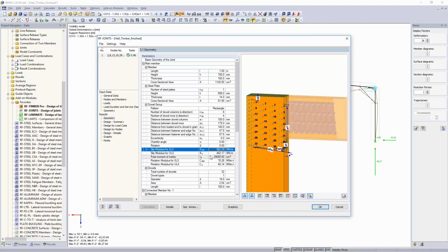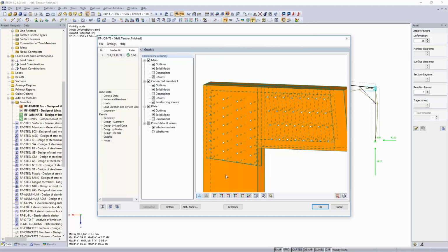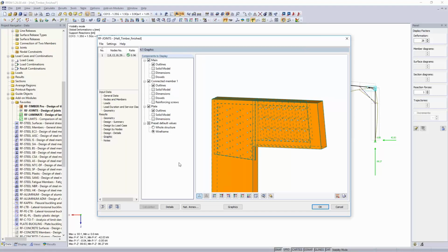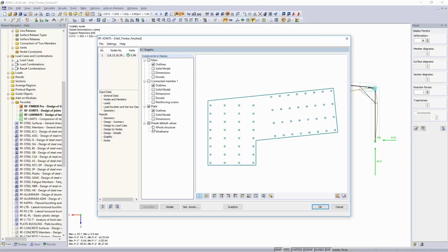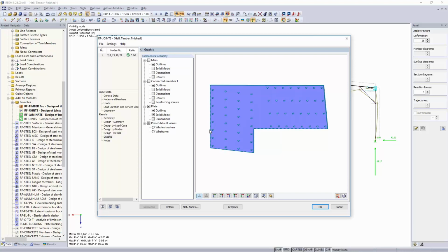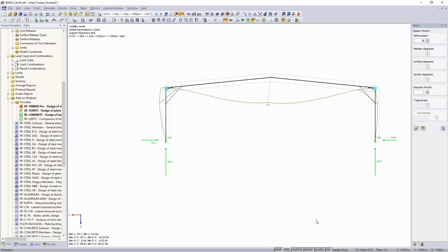Is it similar or different for SLS and ULS situations? It's the same equation, 2.1, according to Eurocode 5, and it exports that for every load combination differently. You can also export a DXF or a plot, maybe when you just want to export the plate to something. You can also export to your CNC and create a shop drawing of it as well. Yes, we can check connections also for fire, as I said when I introduced it, but with a simplified approach.